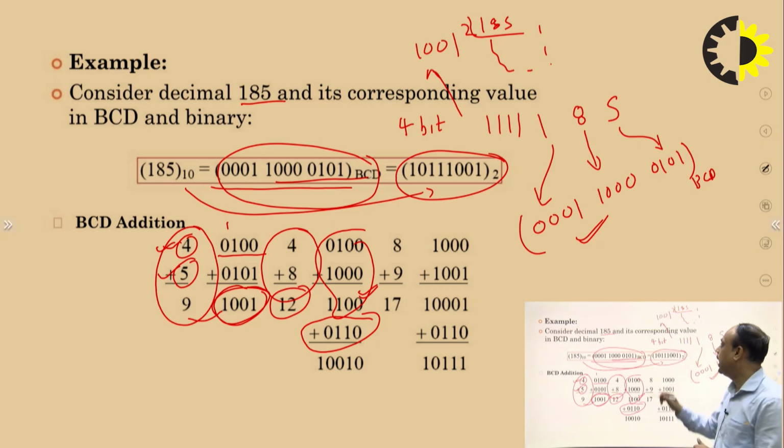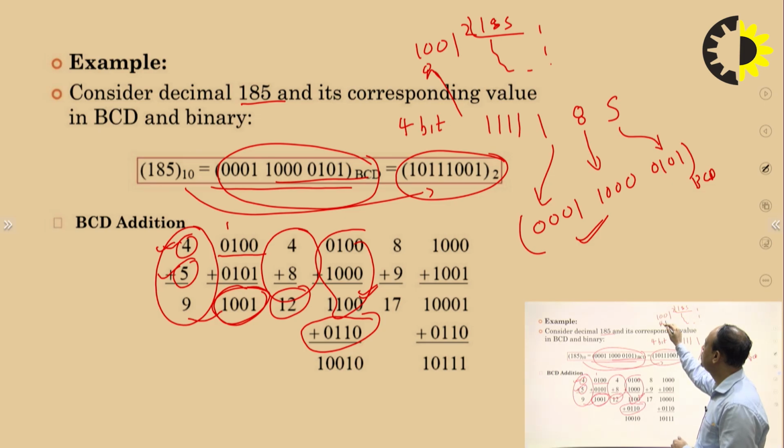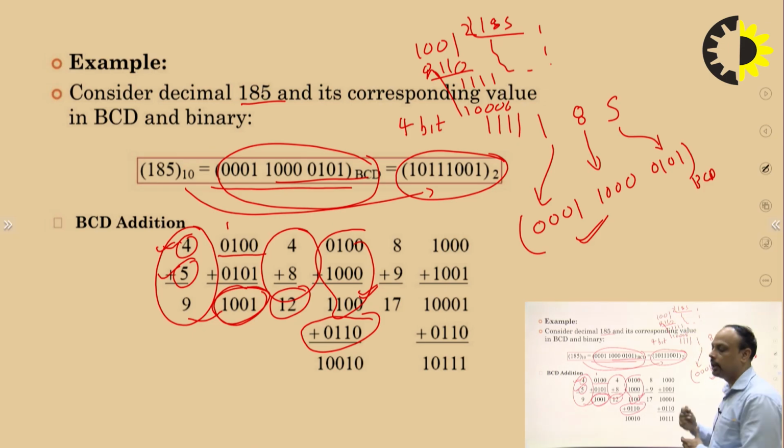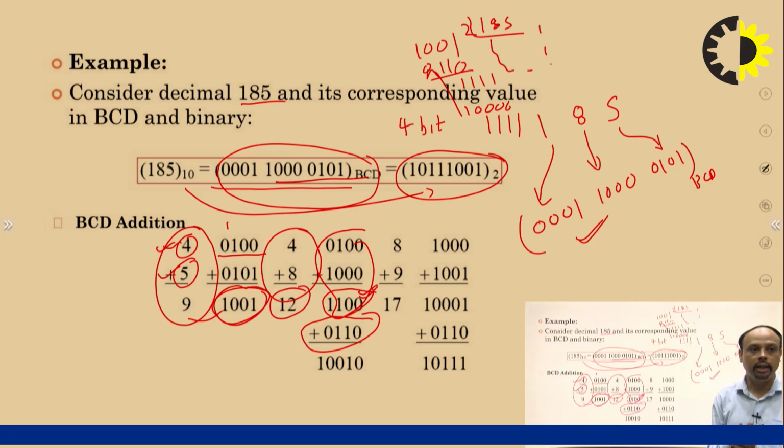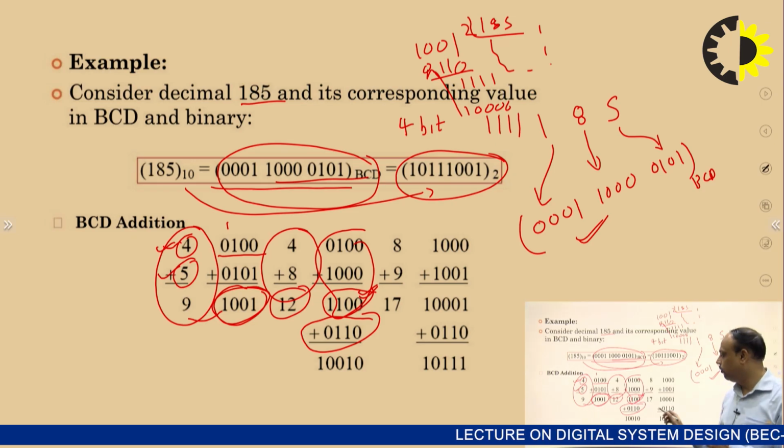So if we add 6 to this, we get the maximum value, that is 1111, and after this 1 bit is extended and the series starts repeating itself. As we can see over here, this is a number greater than 9. So if you want to convert this number into a sum in the range from 0 to 9, we have to add 6.